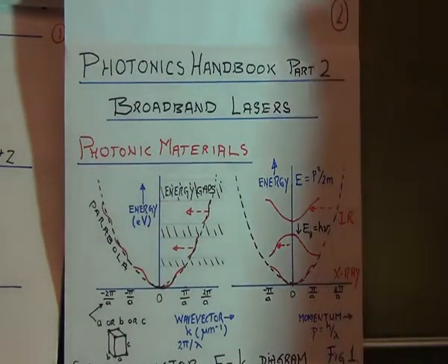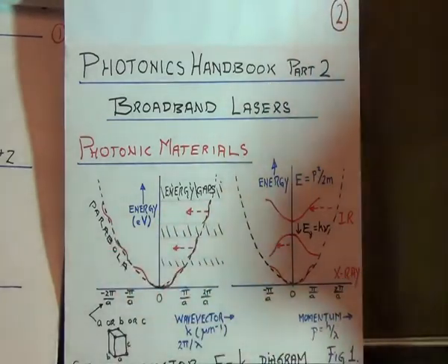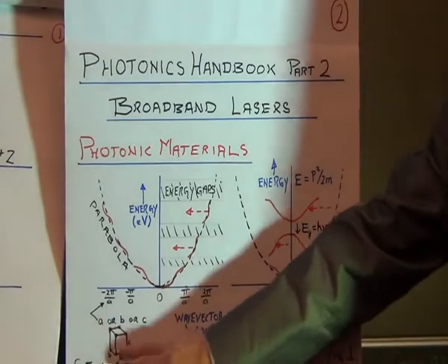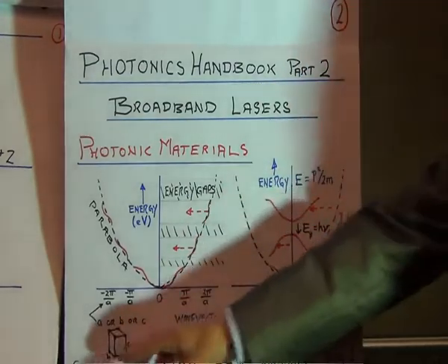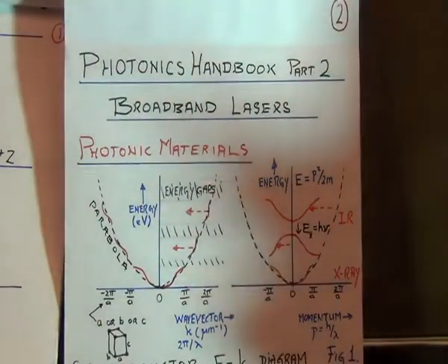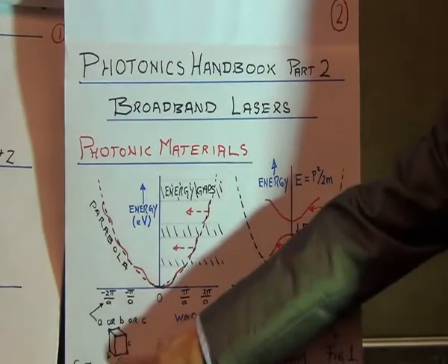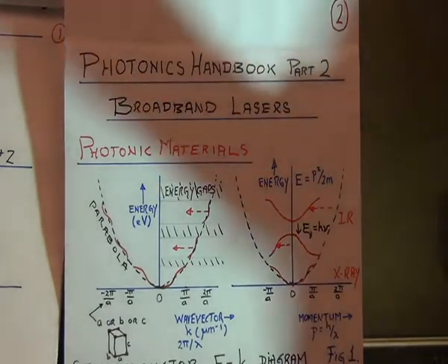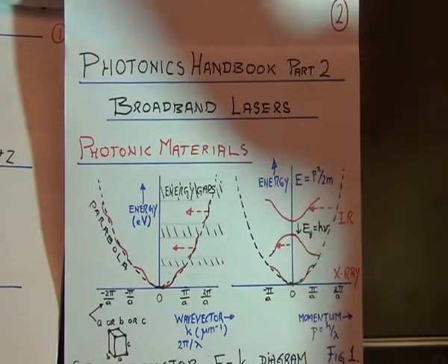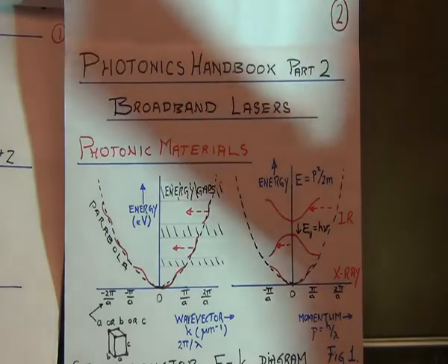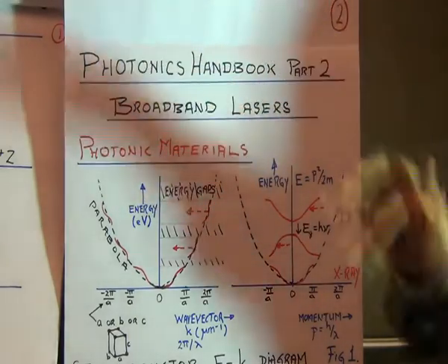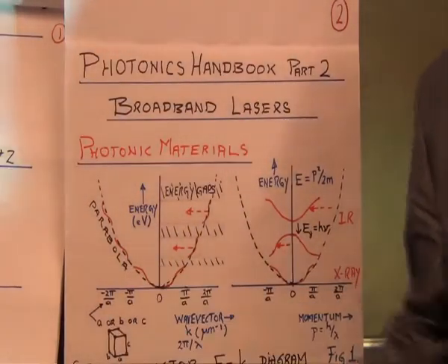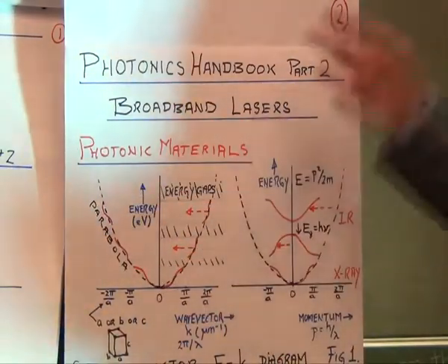However, it is convenient to actually use k to see what's going on, because when you take the potential in this crystal, we no longer have a free electron. We have an electron in a potential that's rising and falling and rising and falling according to the unit cell dimension a. So V(x) is equal to V(x plus a), V(x plus 2a), and so on. It keeps repeating. And you put an electron into that electrical environment, the band diagram changes.